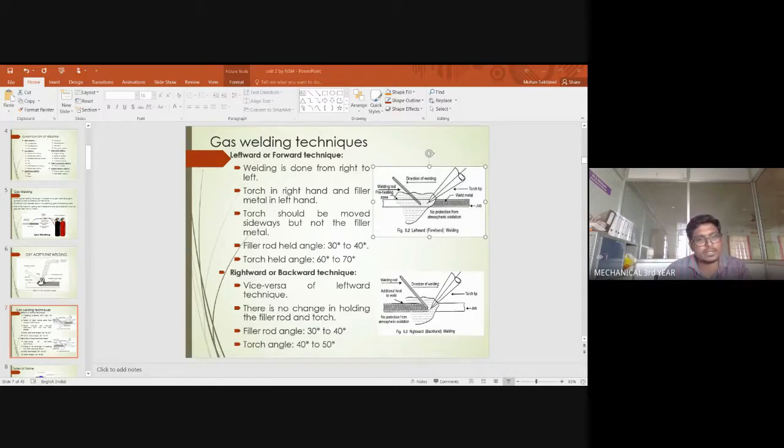Since the tungsten electrode is a non-consumable electrode, we are using a filler rod over here, whereas in this particular diagram you can see the absence of a filler rod, but there is a presence of a wire reel for continuous feeding of the electrode. So let us see what points are available. The electrode holder holds a consumable metal wire electrode which is continuously fed from the reel feed unit.